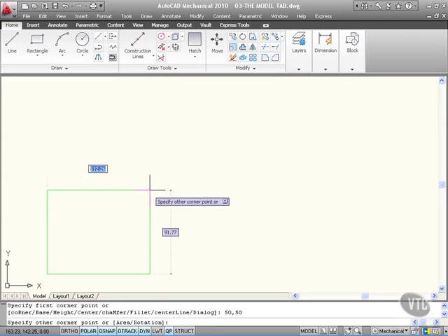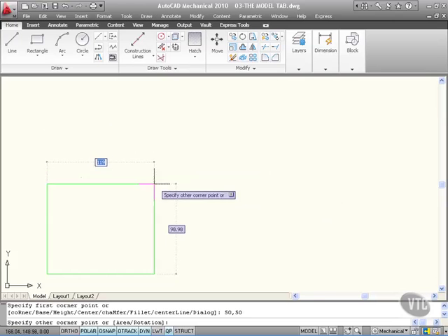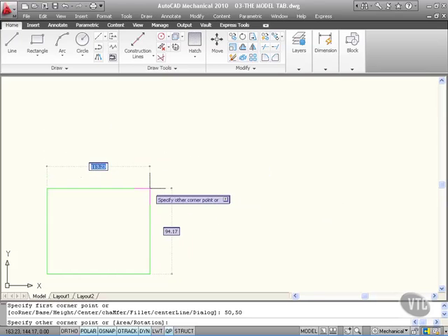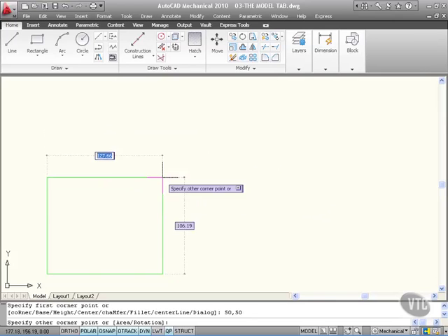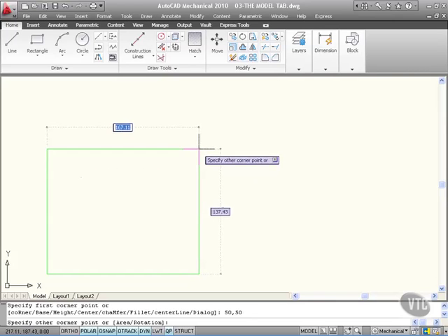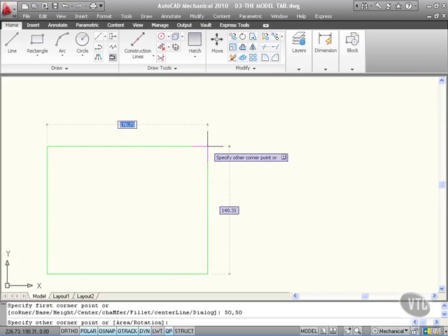Now, as I come away, this is what I love about dynamic input on AutoCAD. Dynamic input has been around since AutoCAD 2006, and as you can see, as I move the rectangle, it gives me the sizes of my rectangle. So there's my side. I want that top side, see the blue there? As I move the horizontal distance, I want to be 250. So I'll type in 250.